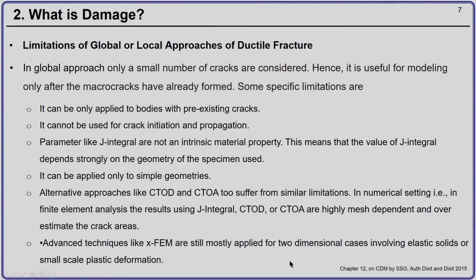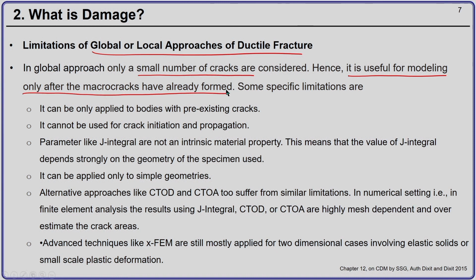Now, there are certain limitations associated with the global and local approaches of ductile fracture. In the global approach you can only model a small number of cracks, and hence it is useful for modeling only after the macro cracks have already formed.